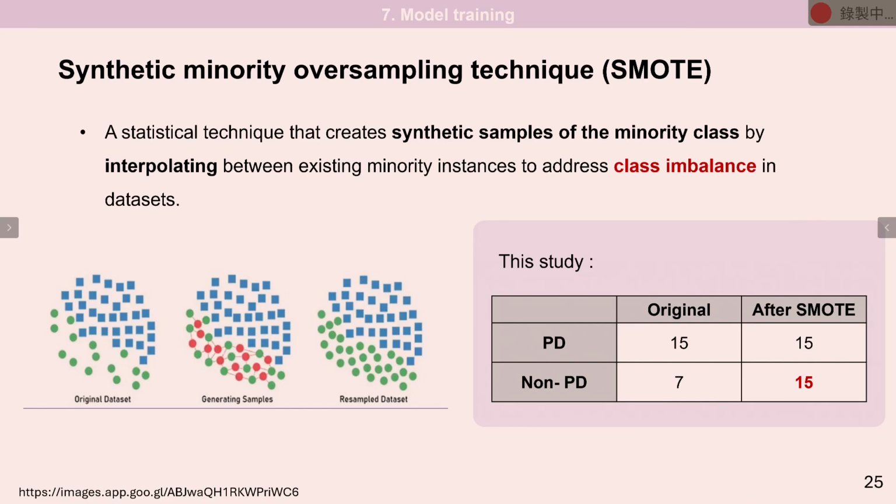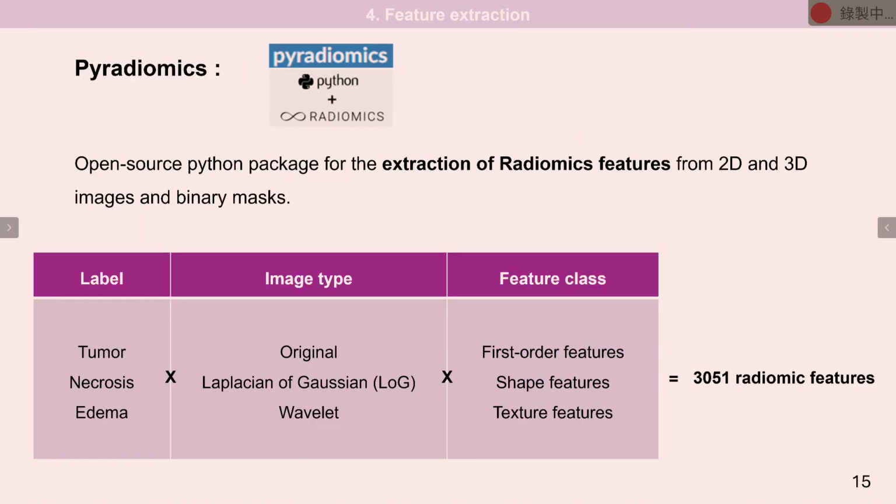The Laplacian of Gaussian filter is a technique used in image processing for edge detection. Its main function is to highlight the regions of rapid intensity change, and it can effectively detect edges. This filter can also help in reducing noise while preserving important detail in the image.